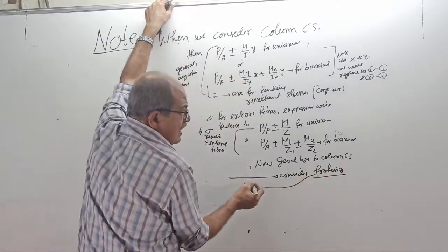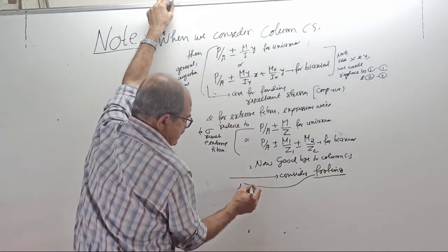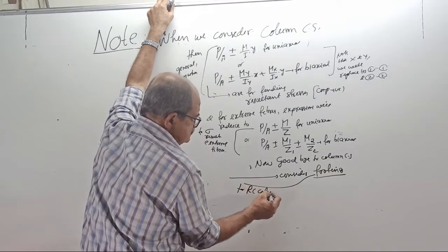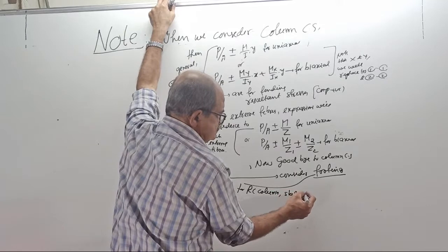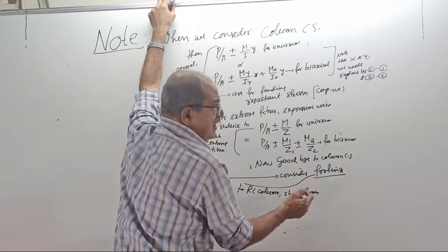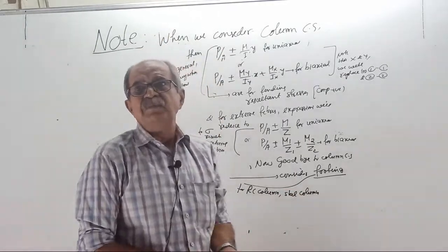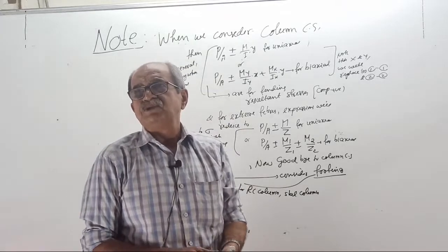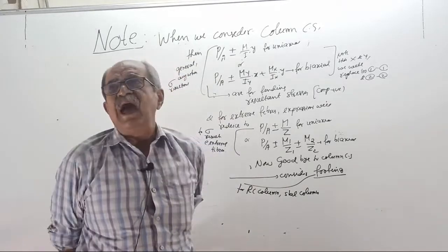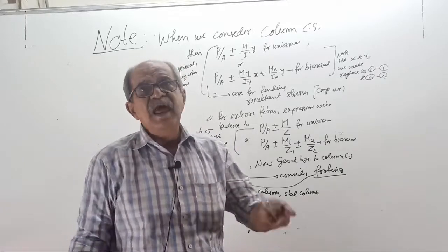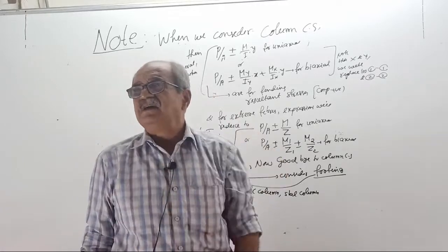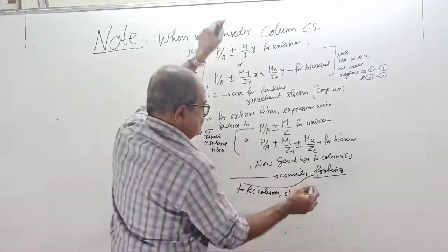Footing can be either for an RC column or for a steel column. If it is a steel column, the column will be placed on a base plate. Then the contact is from the steel plate to the concrete pedestal, later pedestal to soil.